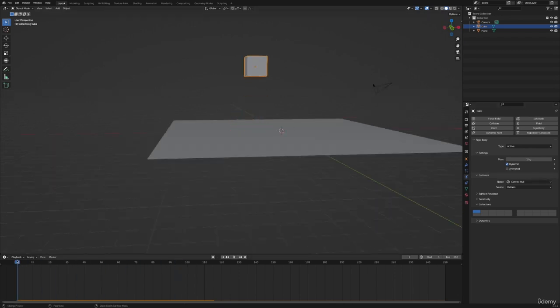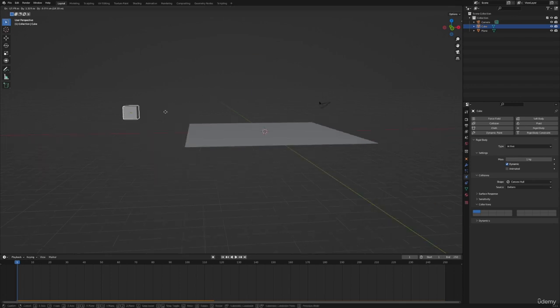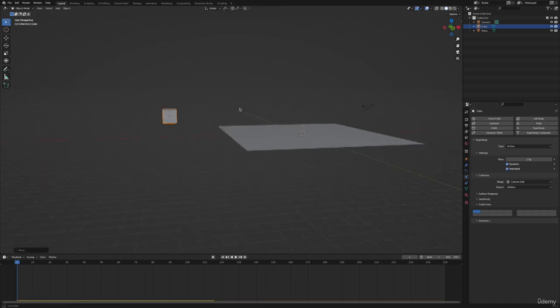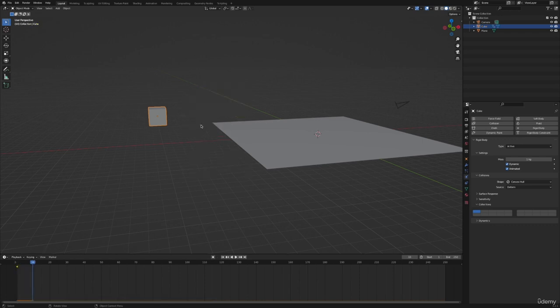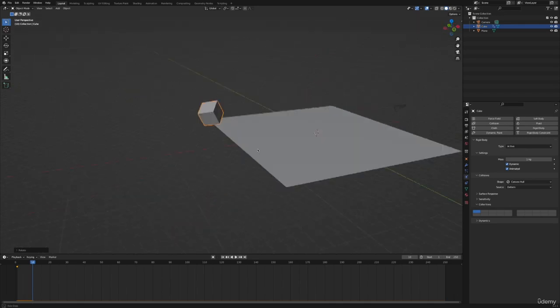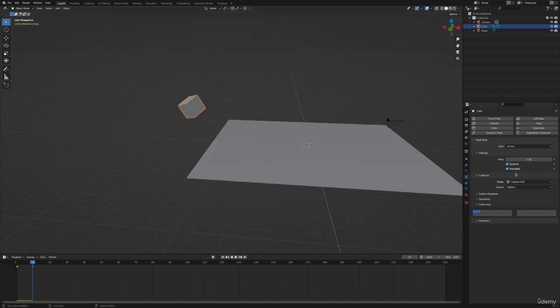Now, I'm going to show you that very briefly. This means that we want our cube to come in here from the left. We'll now activate animated, which means we want to set a keyframe here for the location and the rotation, and then set a keyframe at 10 for the location, and then the rotation again, of course, and we just spin our cube a little bit like this. Now, what I want to do is let the animation play until frame 9, but stop at frame 10. So we make a keyframe at frame 9, then we go to keyframe 10, and it should then be deactivated.